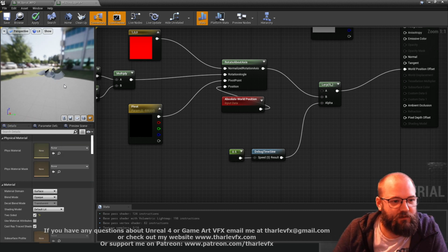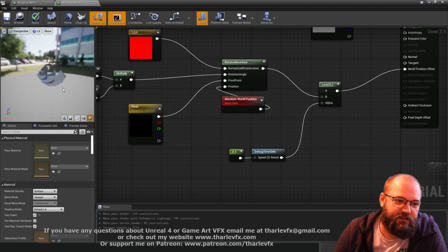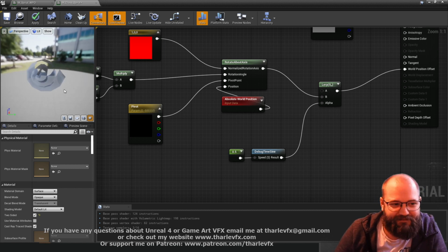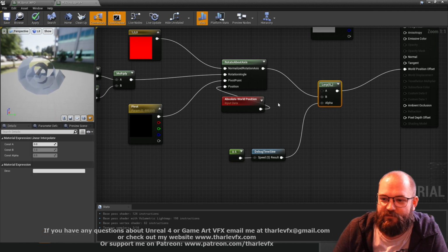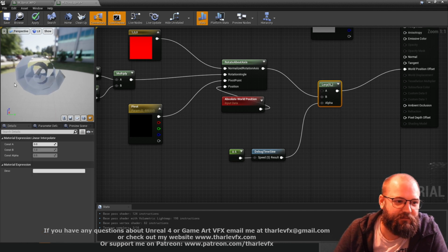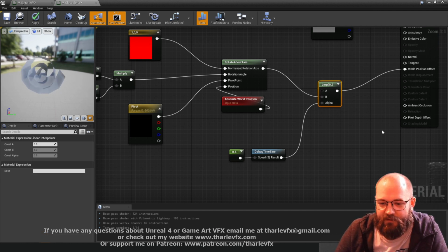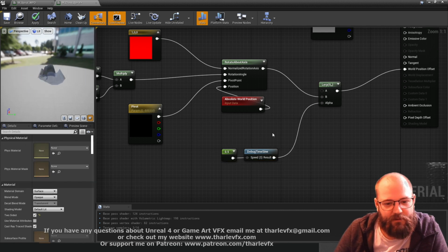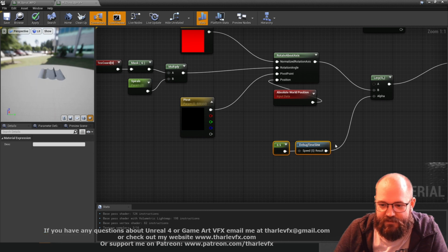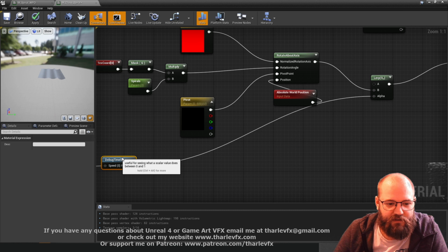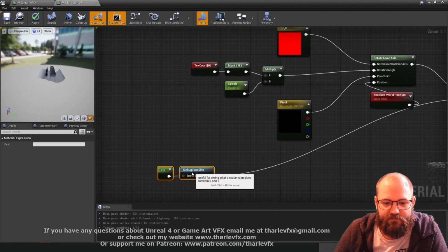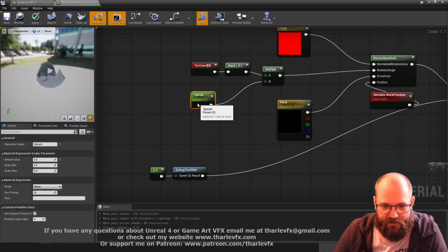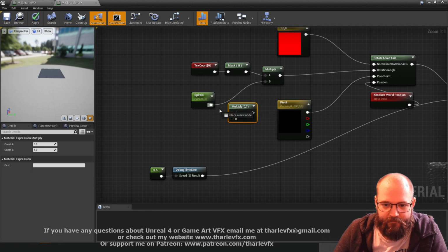Now this is sort of doing what we want. We have our 2 endpoints the same, but not quite right. As you can see, it's a linear movement, so it's linearly changing from the spiral shape to the flat shape, which isn't really what we want, but we can work with this. And so the same values that I'm using to blend between my 2 shapes, I'm also going to use to blend how many spirals I've got. So I multiply my number of spirals by my animated value.